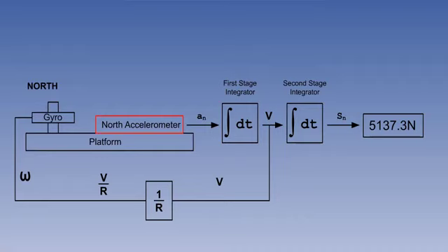Accelerometer bias is next. The accelerometers are designed to give 0 output for 0 input, if properly levelled. However, due to manufacturing imperfections, there may be some slight output when the accelerometer is perfectly stationary and level. This is called accelerometer bias.